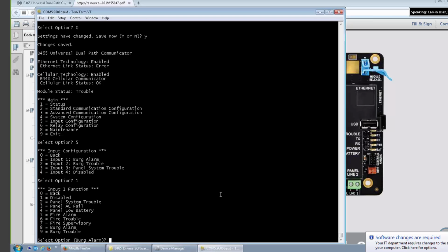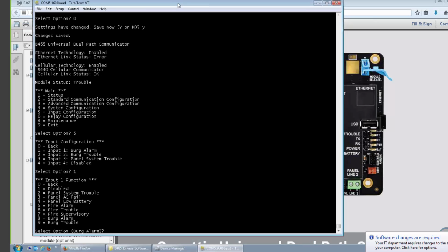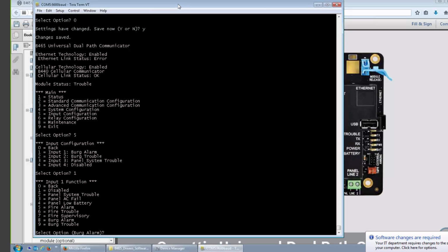Is this thing listed for fire as a fire alarm panel? I don't think it's listed as a fire alarm panel standalone. I'm not sure. I think it's intended to be used as a slave communicator, but I'm not really sure if that's something that would be a problem to just throw it in there if you wanted to only monitor 3 or 4 points. You might be able to get away with it.